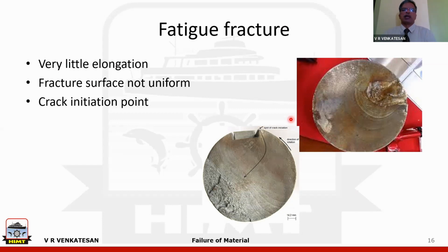So there's always some kind of a fracture or crack initiation point. And very often they come from the surface, not all the time, but if the inside part of the component has some defects like a blowhole or any such discontinuity inside, then it can start from there also. But very often it starts from the surface, from the initiation part.